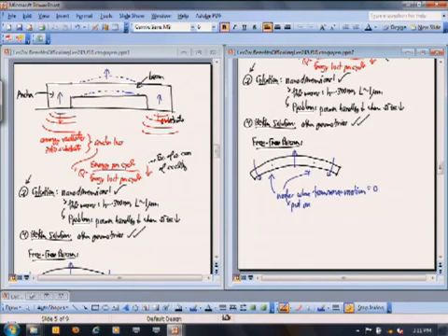Yes? What's the advantage of that design compared to just a single support in the middle? Single support, it depends on how your beams flap on those, because if the beams are flapping both directions at the same time, then you're going to be pumping your substrate still. But if the beams are doing this, then it's slightly better, but you still will get some rocking motion into the substrate. In this case, there's actually still rocking motion happening in the supports.